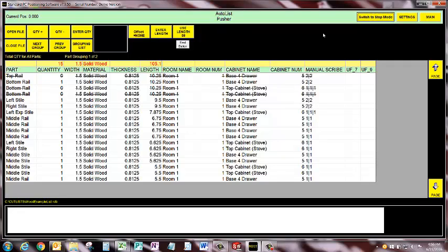you can have secondary operations. So let's say you're a cabinet maker and you have one of the cabinet design softwares that outputs a cut list that has scribing information, and by scribing I mean joint location, where on a face frame the locations of all the joints are. That information is now in several cut lists because of the RazorGage pocket hole machine that has the scribing capability, and so many software vendors have added this to their cut list.